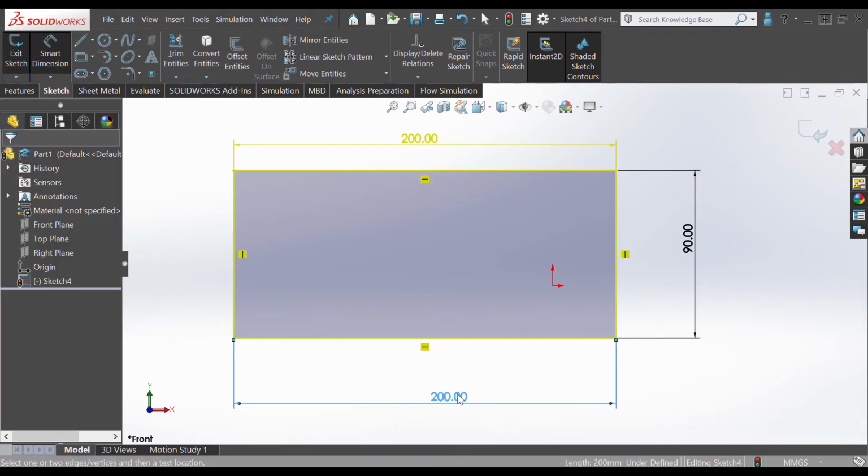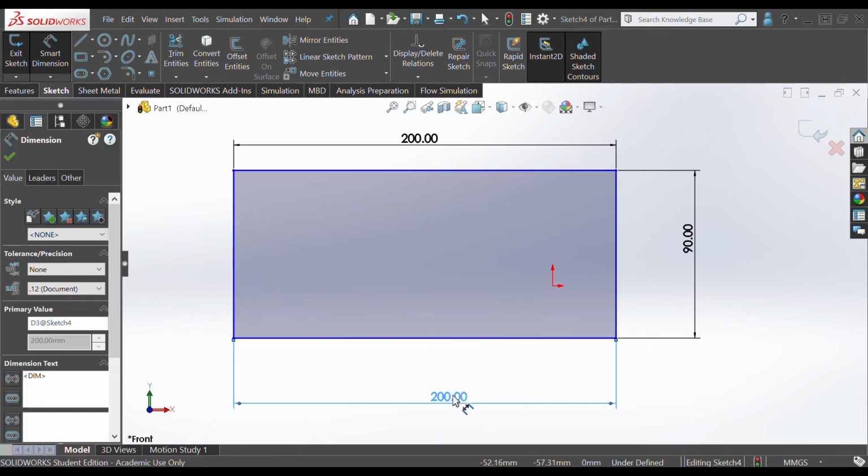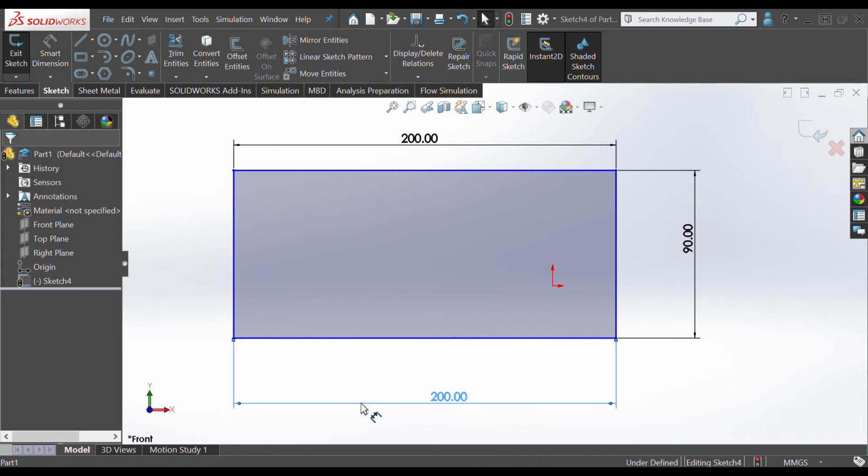This one. So I can see after I chose 200 again, it says that this is a rectangle and I've chosen 200 originally. So if I chose another 200 here, that means I'm over defining the figure, which is something we don't want. So we're just gonna press OK for now. Just go over this and just delete it. So as you can see, we've dimensioned this side and that side.